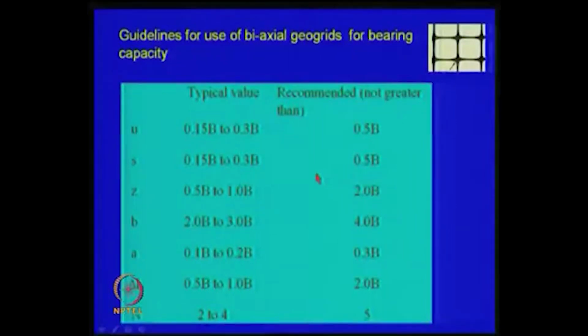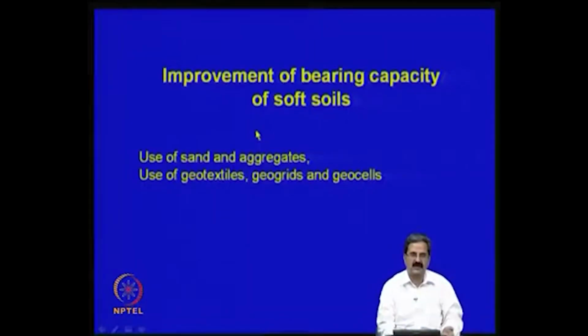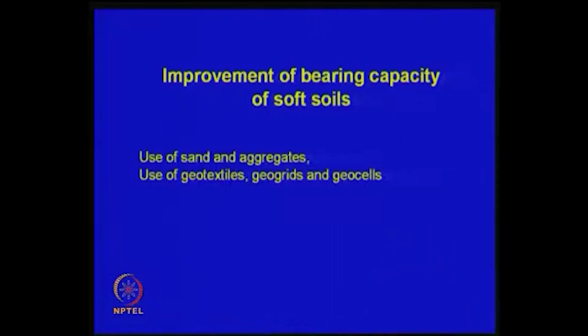So additional information on this would be that we will handle what you have seen in the case of soft soil, the sands, how the bearing capacity could be improved, and the bearing capacity could be improved, as I just mentioned, because of the actual response of the reinforcement element. We have tensile force developed, we also have frictional, because the tensile forces are developed because of friction and also the bond resistance.